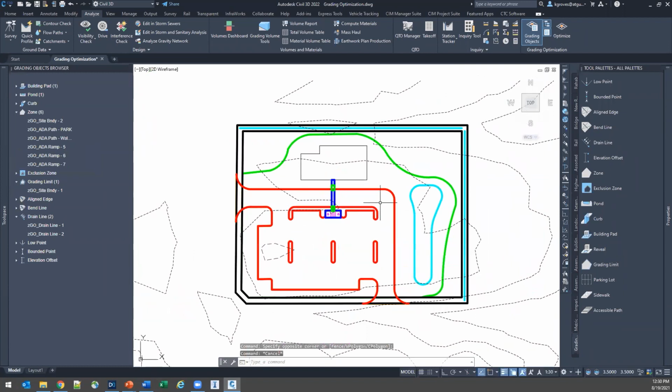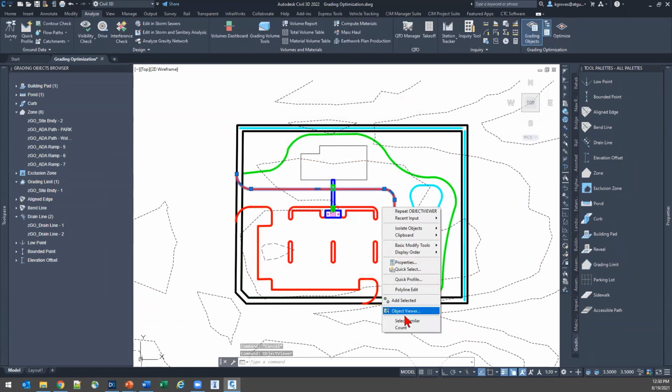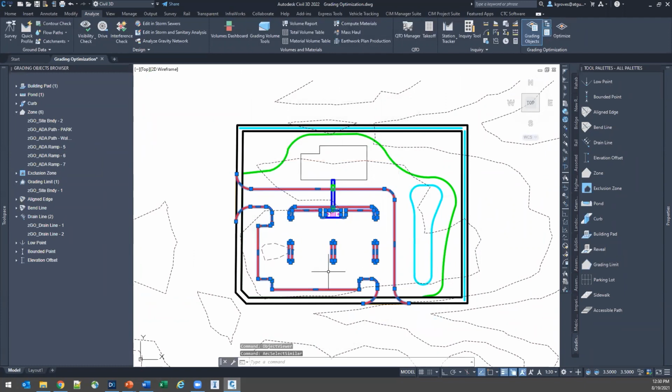I think the last thing we need to do is our curb. Sorry, 2 more things: curb, then pavement area. So all these curb lines, pretty straightforward. I'll just select similar. So curbs can be both area data and linear data. The tool treats lines a little silly, so I might recommend doing a real brief offset and closing it. But I'm going to just go ahead and grab both of those.